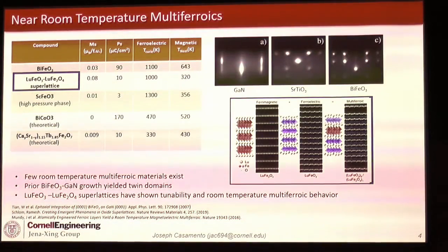There's a need for intervening strontium titanate and titanium dioxide buffer layers, which still, the resulting film is epitaxial, but it results in a 180-degree twin variance when grown directly on GaN. So that in itself wasn't promising for epitaxial MBE growth.